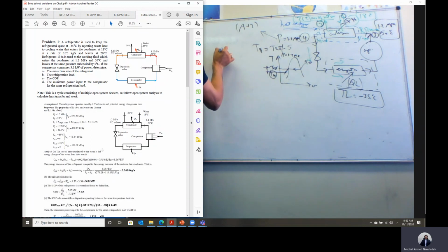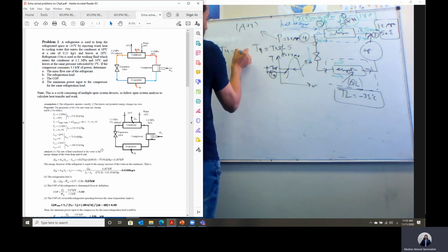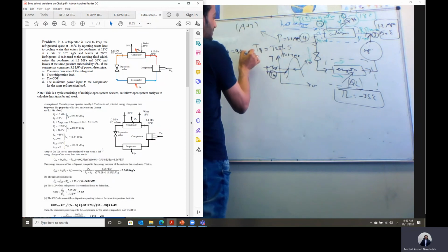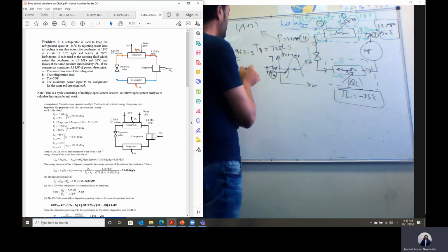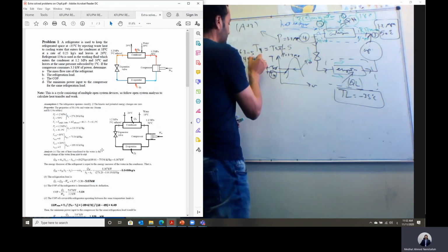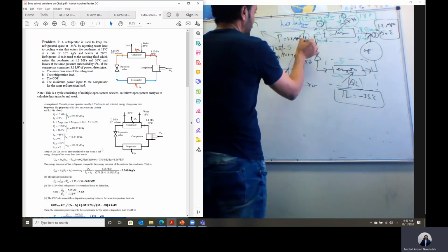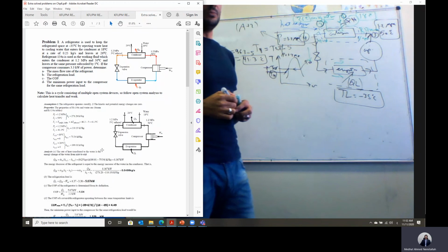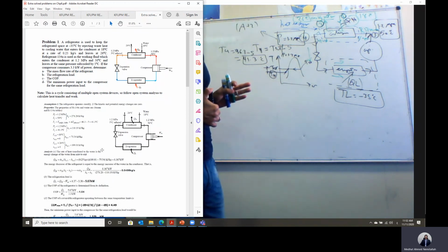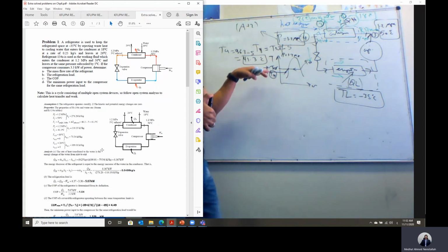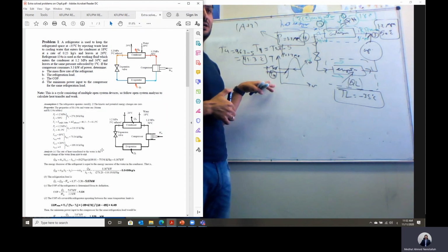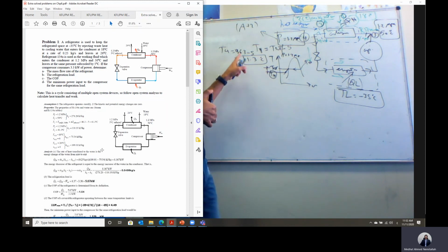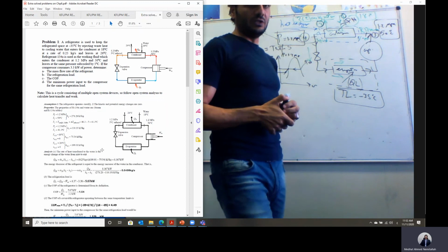So the temperature T4 will equal 46.3 minus 5, which is 41.3 degrees Celsius. This is the temperature and pressure at state 4, and this is the idea initially. If you are told the temperature is subcooled by 5 degrees C, that means the temperature at the outlet is less than the saturation temperature at the given pressure by 5 degrees C.